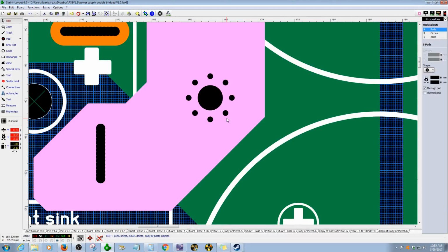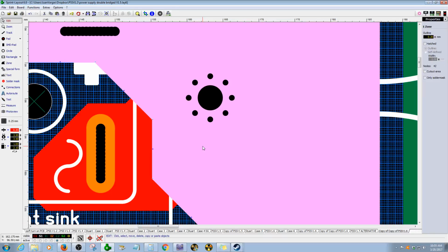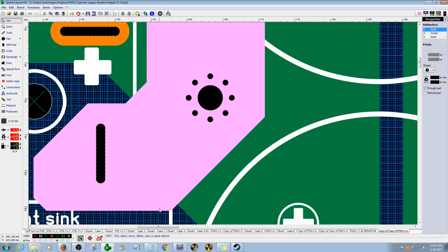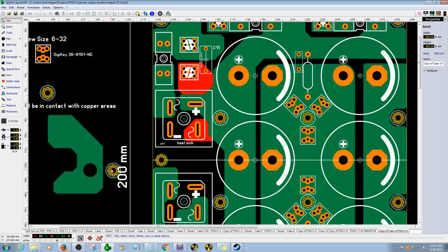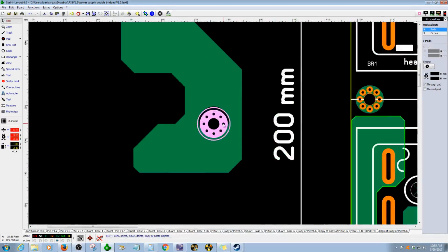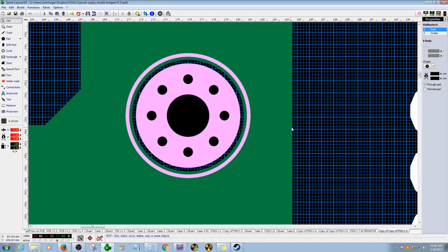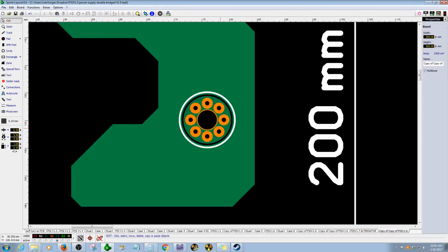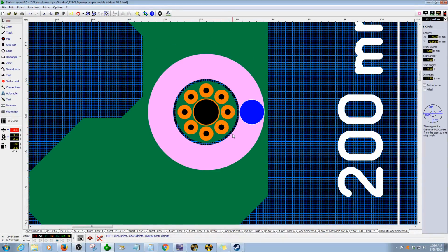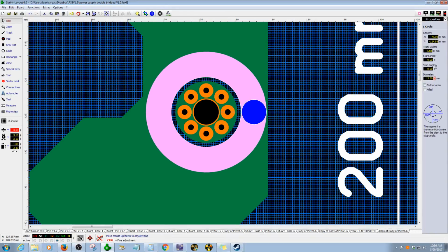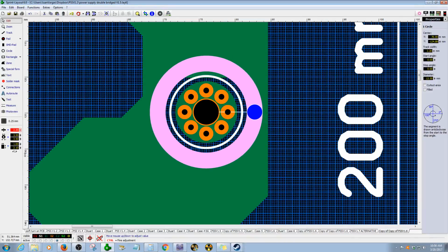It won't let me take it. Oh yeah, I forgot that I split the group, and then I can select this standoff just to see how much space we need. I think I gotta make it larger. We need to avoid any contact with the copper area, because there is voltage involved there, so that's a pretty dangerous situation right there. Okay, almost close. I think I got it.